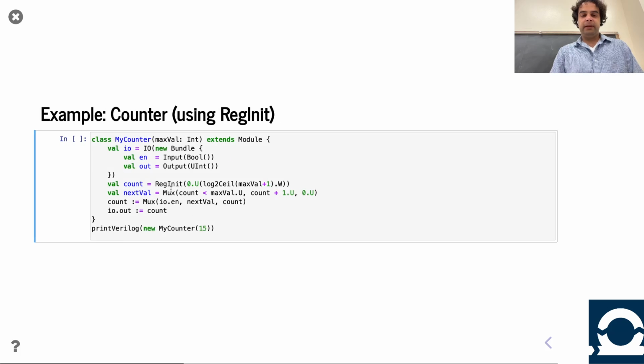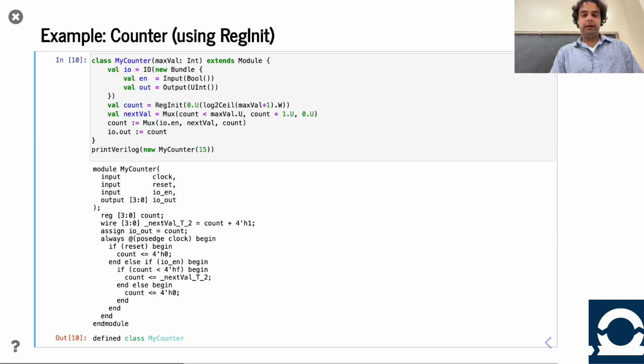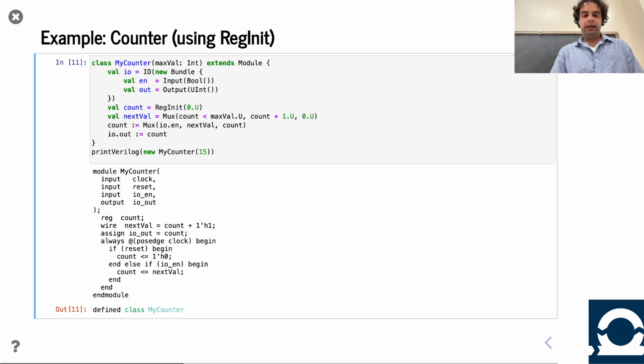So we did that. Now we have RegInit. It does the right thing. It all comes together there. Cool. One less mux, so it handles the reset for us. So this Verilog is basically the same. Now, one person may ask, well, gee, what happens if I don't specify the width here? Say the default value is 0, which is a reasonable thing to say. It's going to kind of work, and where it breaks is that the tool is under-constrained for that counter. It doesn't know how big it is because it doesn't see the maximum value.